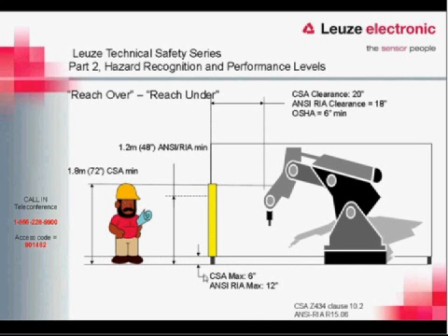So according to the various standards we have, CSA, ANSI, OSHA, they all have a little bit different specs, and we'll go into that more in the next webinar, which is safety distance calculations. But we'll touch on it a little bit here. So if we are 1.2 meters off of the ground with a maximum opening of 6 inches, which is mostly for hard guarding, 12 inches usually for AOPD devices, then that gives us a distance of 3 feet that we're allowed to be away.